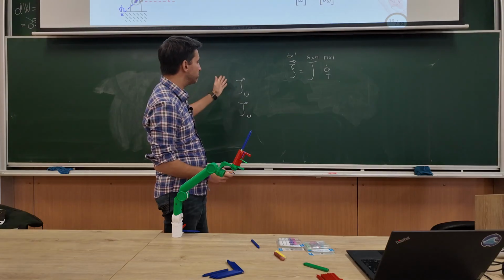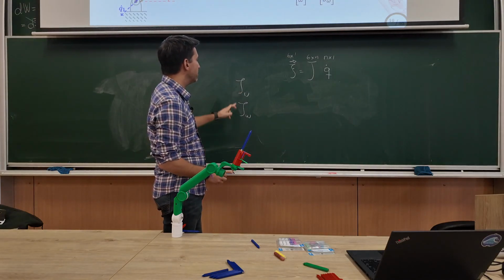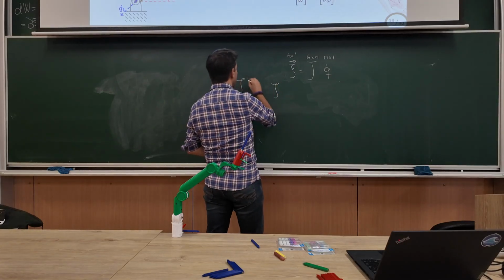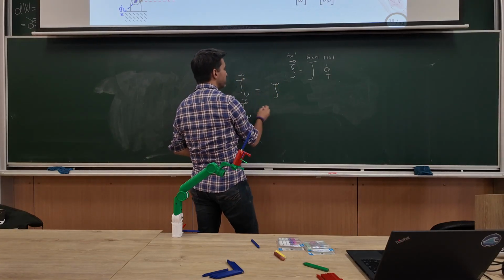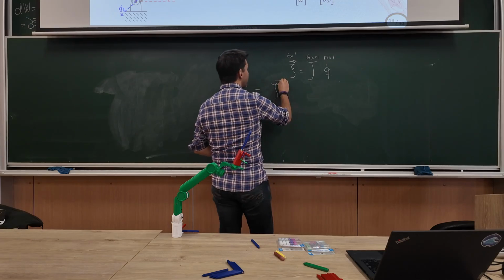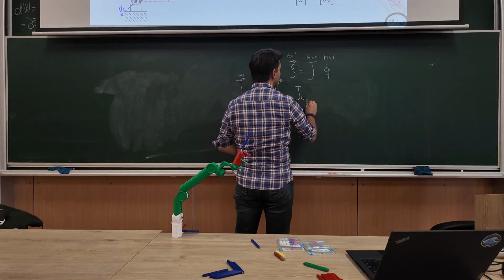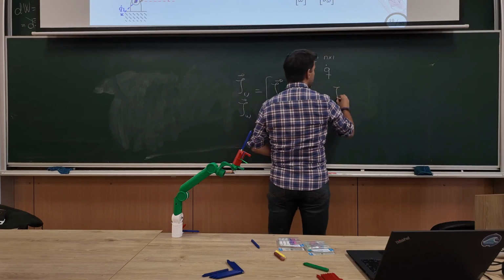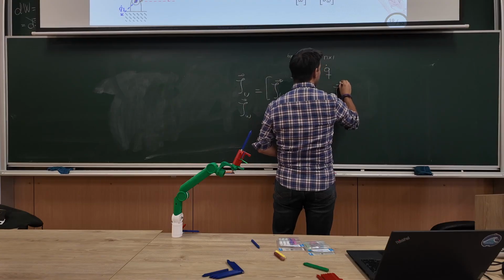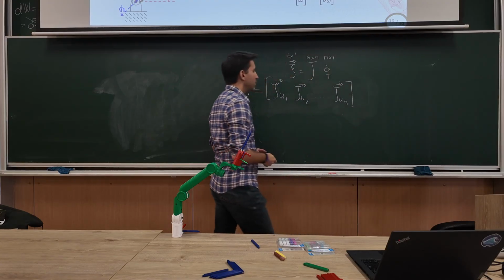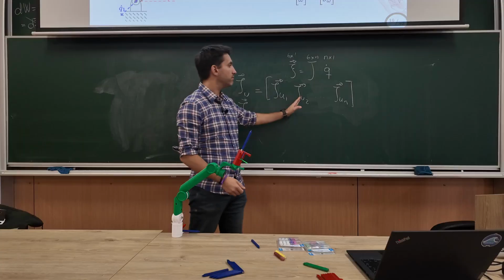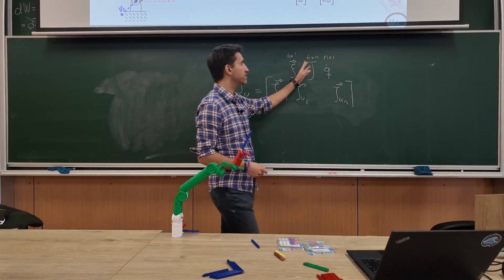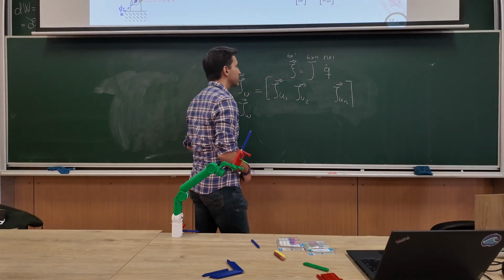These two submatrices we can write as vectors, Ju1, Ju2, right, Jun. So we have n direction vectors, one for each joint. That's why it has n columns.